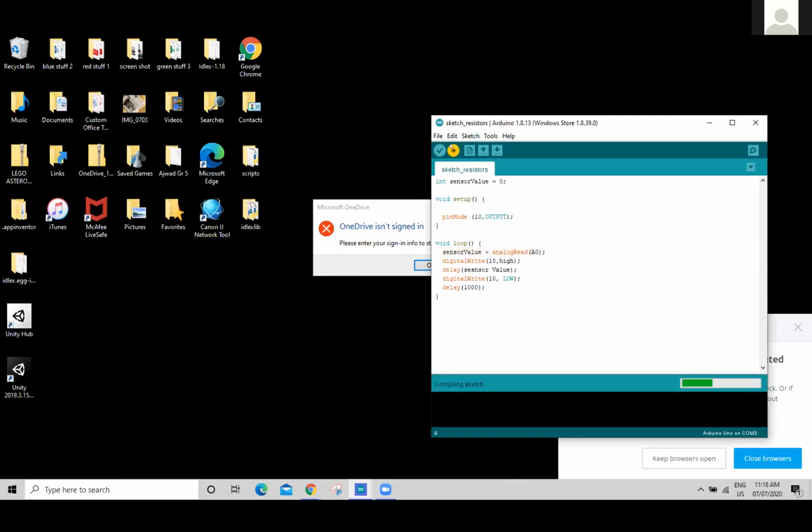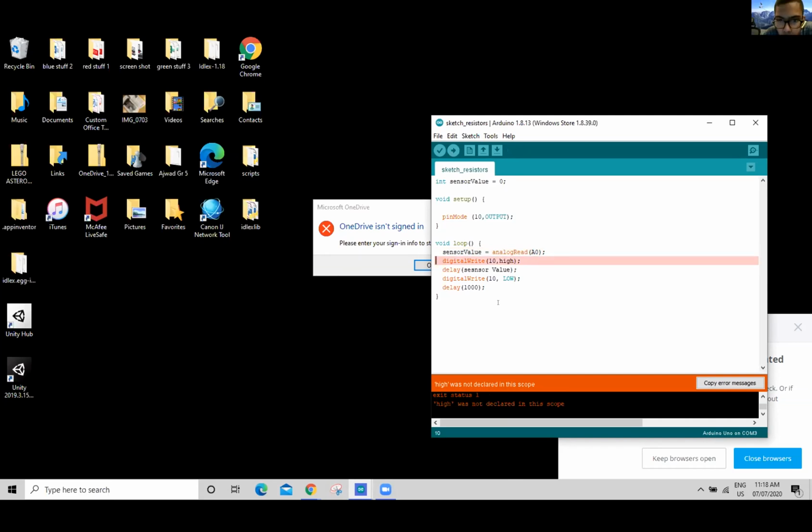It's not working. It's digital write and HIGH. HIGH is supposed to be capital. All letters should be capital, just like LOW, right? Serial port not selected is the same thing we were talking about before. It's a service command, so it's supposed to be the same as the LOW. Yeah, here is where you have to be meticulous. It's supposed to change color, you see? HIGH is now blue, so it's supposed to work now. That kind of helps you, right? Also, it has to be the same in each row as well.